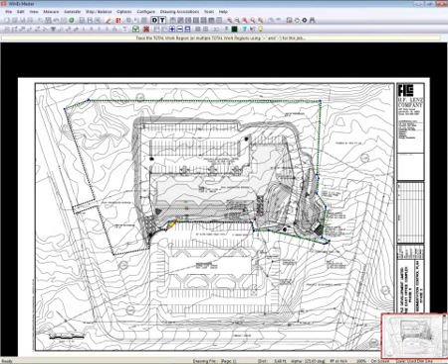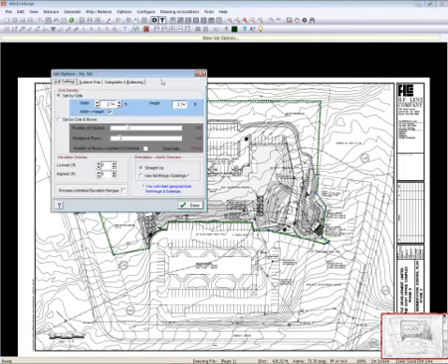And you'll notice when you come to a curve, if you hold your left mouse button down, it brings up a zoom box around the pencil that you can trace. We'll talk more about that later on. That's our line tracker feature. Now, for this last section, you don't need to try to get the last dot right up to this. If you go up to our Finish button, which is located right up here, and click on Finish, not only will the software finish enclosing your total work area, but it will bring up your job settings window. So I'm going to do that.